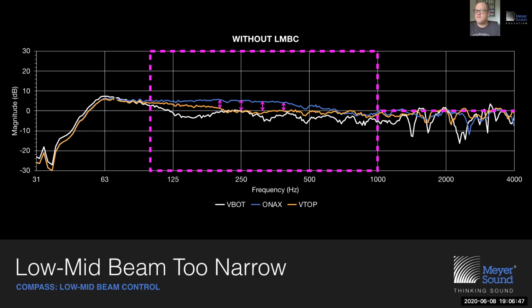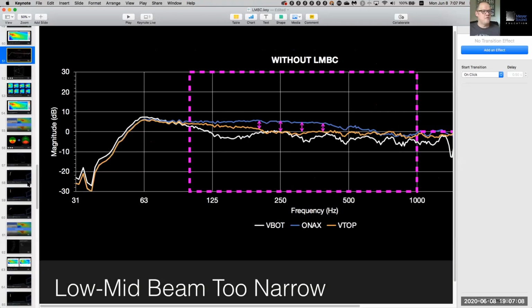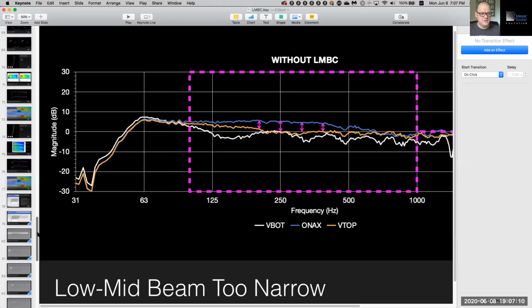So it would never be possible to fix this with electronic delay, delaying all frequencies equally applied at different amounts to every element in the array. However, carefully arranged all-pass filters will allow you to electronically increase the curvature of your array, spreading the beam electronically, but only for very select frequencies.